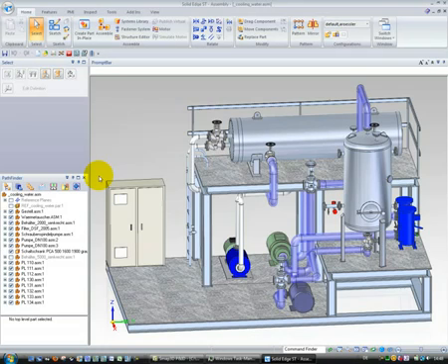The heat exchanger, for example, is imported from a STEP file from a supplier web page, and the vessel, for example, is modeled and created with pure Solid Edge modeling functionality. All these components and equipment are necessary to create and assemble before you start the 3D pipeline creation, and it is done with pure Solid Edge functionality.